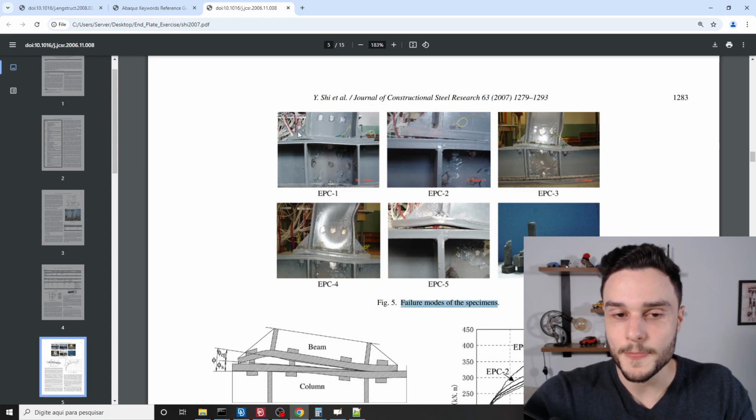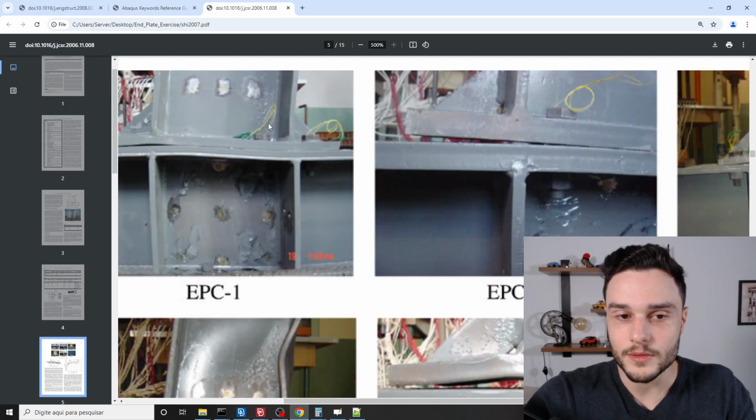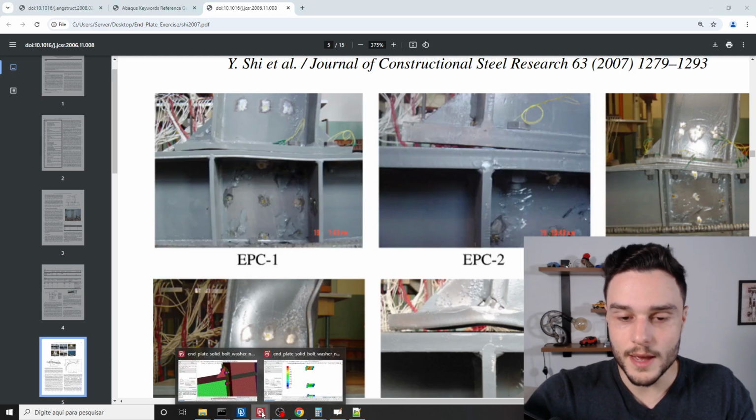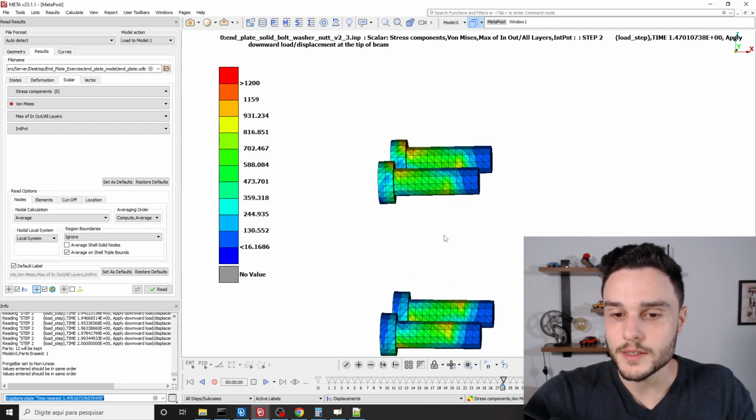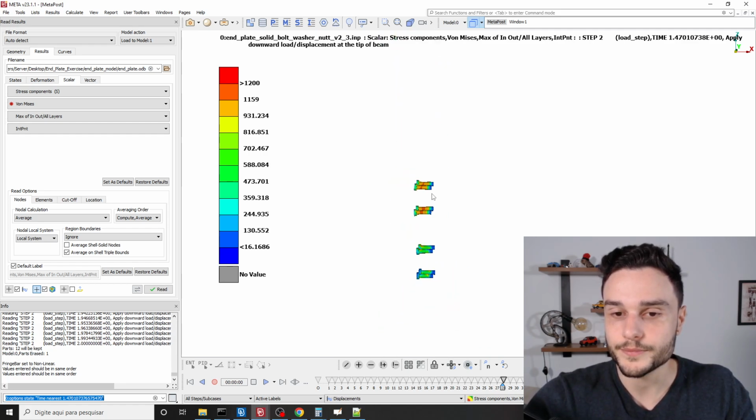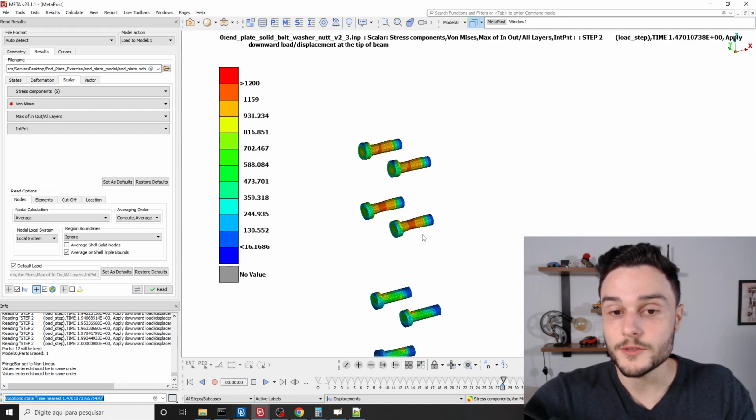And then you see that these bolts in this region don't exist. So these bolts separated in two, we had failure of these 4 bolts here, while we yet have these bolts in here. Okay, which is what is happening in this model. We have these 4 bolts failing, and these bolts are yet here. Okay, so this model is representing pretty well what's happening in reality.